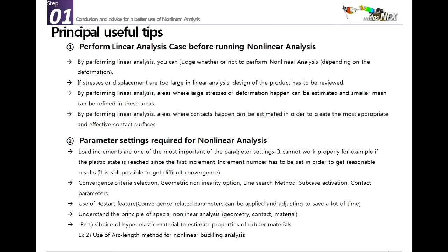Parameter settings are required for nonlinear analysis. Load increments are one of the most important of the parameter settings. So you should care about that. The number of load increments is important. If you don't get convergence, you can always increase the load increments and see what happens.